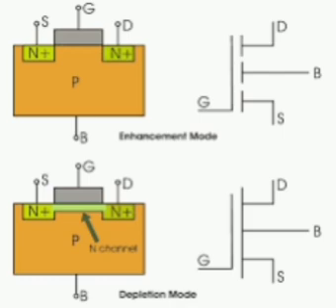Varactor diode: a PN junction diode that changes its capacitance as the bias applied to the diode is varied, operated under reverse bias, used mainly in tuning applications and in low noise microwave devices. C is directly proportional to 1 by junction potential to the power m. m equals 1/3 for linear graded junction, m equals 1/2 for abrupt junction. Used as a low noise amplifier, parametric amplifier.